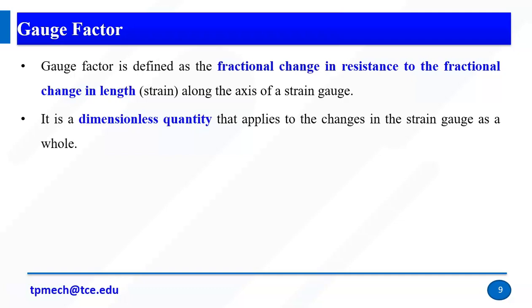It is a very simple principle. If I supply voltage or electric current, I get an output, right? The output will be uniform when there is no strain. If any strain occurs, the output will change because the length changes. When I apply strain, the length changes, and when the length changes, the resistance changes. When the resistance changes in the electric flow, the output voltage will automatically reduce.